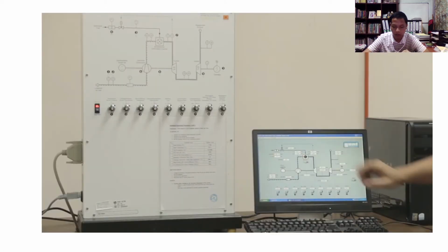Next, continue the experiment by changing the load on the power turbine from 30% to 100%, in increments of 10%. Then proceed to change the gas generator efficiency, which is the high pressure efficiency, from 60% to 100% with increments of 10%, and also change the power turbine efficiency, which is low pressure, from 60% to 100% with increments of 10%.